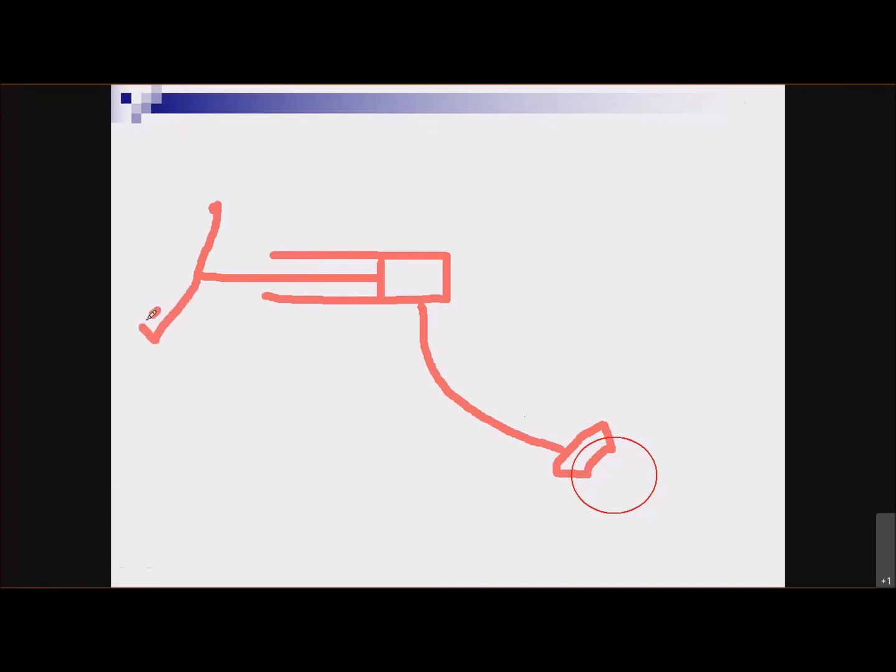There's our caliper. So a normal braking system without ABS, what do we have? We have a master cylinder, right? So there's the cylinder. There's a piston inside it. And then there's a steel line, rubber hose going from that brake master cylinder. And of course, here you have your brake pedal.